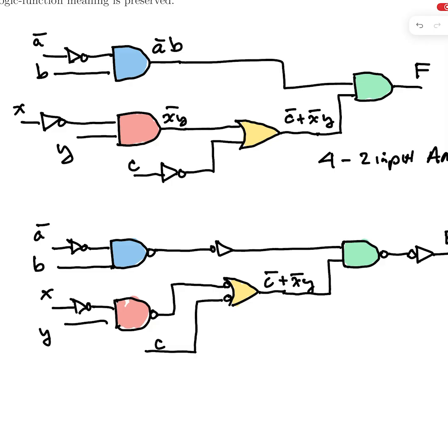Now, in a previous section, we talked about how these gates with AND and OR are actually formed from NAND and NOR. So you have the NAND followed by an inverter. So that would have 4 transistors on the NAND part, and then another 2 transistors for the inversion. So that's 6 transistors for each of these.